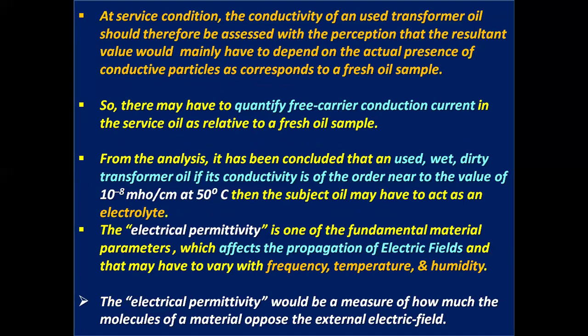At service condition, the conductivity of a used transformer oil should be assessed with the perception that the resultant value mainly depends on the actual presence of conductive particles as compared to a fresh oil sample.